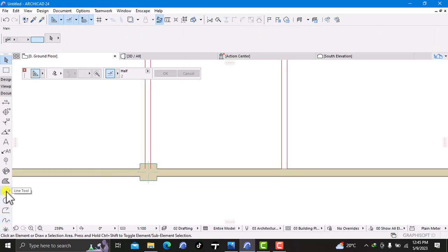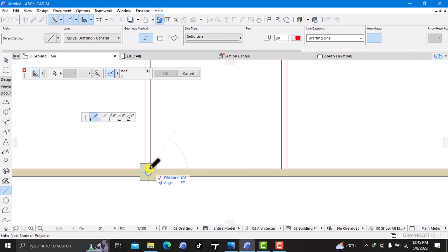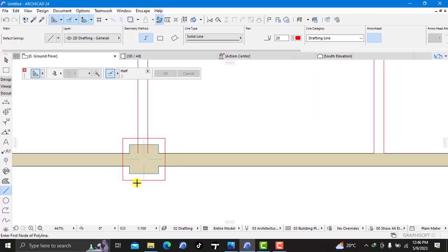In layman's terms, where I come from, it's called a kofia, but it's a coping on top of this. So I'll just do a line all around this, and then go ahead and offset this line. Click the offset tab, use the magic wand and just offset this to a distance of 100, and then you can get rid of this small line over here to allow for space.